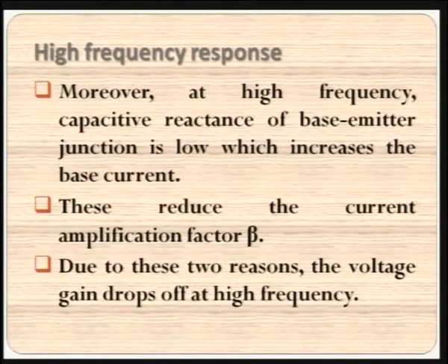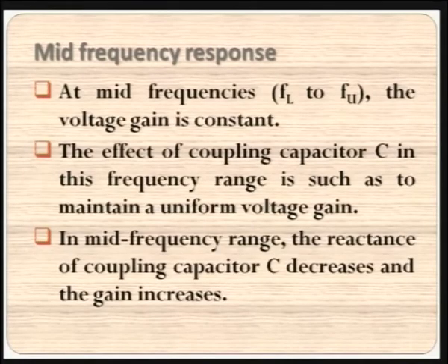Welcome back. At high frequency, the capacitive reactance of the base emitter capacitor that is developed across the junction is also playing a role. Because of that, the gain decreases very much when the frequency increases. Now, it is time for us to see the reason for the behavior at the mid frequency range.